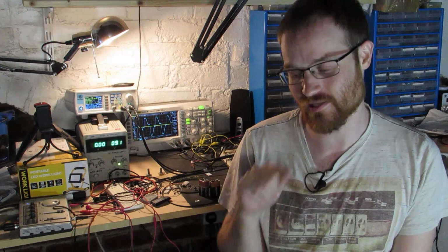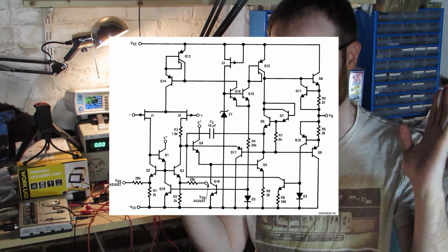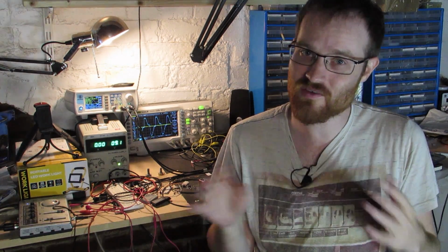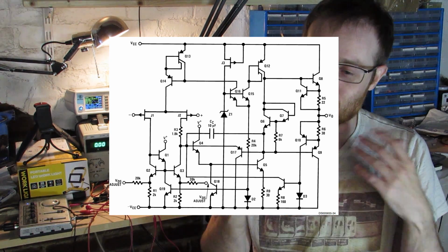Okay, so hopefully I've convinced you of what an op-amp is internally, and what I'm trying to get across in this bit is that while the op-amp schematics look very complicated and terrifying, looking at all these bits, at its core, it's not anything that we can't understand with the things that we've done in these videos so far. It's essentially just a very high gain differential amplifier with a nice low impedance output buffer. All of this other stuff is just improving the circuit performance, making sure we've got lots of gain and it's very stable and all this other stuff.